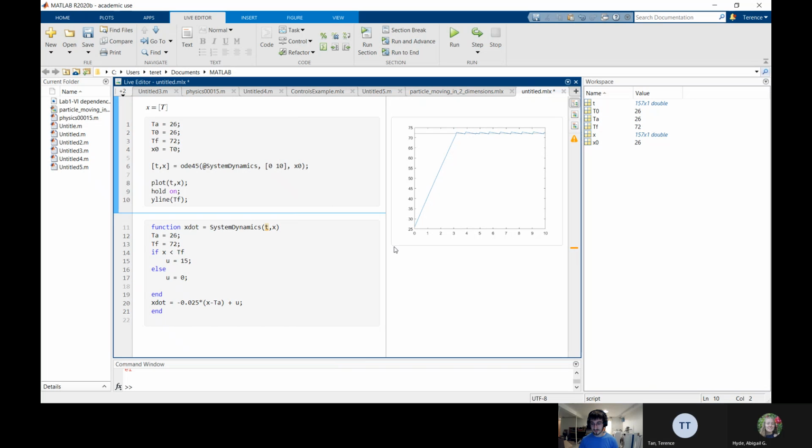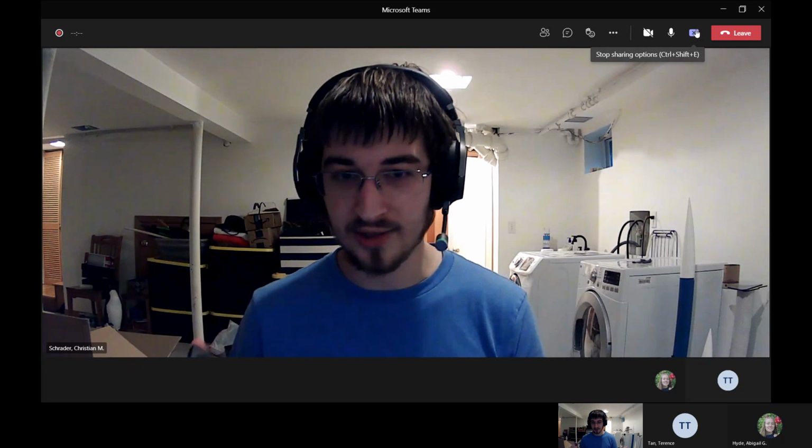So I know we're kind of out of time for today, but my challenge to you is, if you find time, try implementing some of the other types of controllers. Probably try proportional control and see how that compares. Do I just guess those constants for now? Yeah, that's the thing, we don't have an equation that just tells you what K should be. Later on there are methods for getting to a good value quicker. But oftentimes the easiest way is to just guess and check and see if the system behaves the way you want it to and adjust from there.